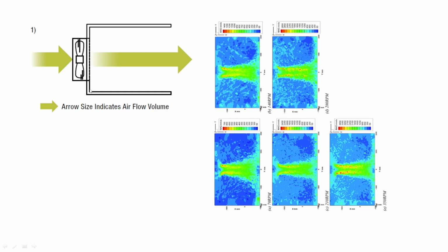But I don't really like CFM airflow testing for looking at case airflow, and the reason is exactly what I just said. It hides the fact that a fan shoots air off to the sides. You're not going to see the data. Fans will look much closer in performance, and you're going to get a fan that isn't going to work the way you want it to.